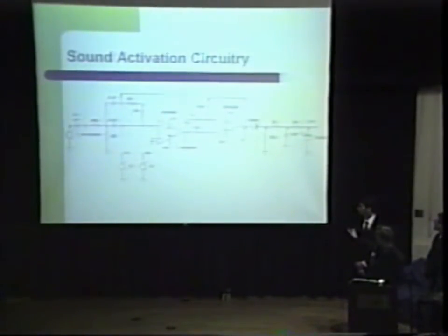And this will cut off any negative portion, leaving a positive DC value. This cap right here holds the sine wave as it goes to a peak, and it slowly discharges through that resistor. This Zener diode out here is a 5.1 volt Zener, so that it would protect the processor. Anything going over 5 volts will destroy it, so we don't want that to happen. That's why that's there.